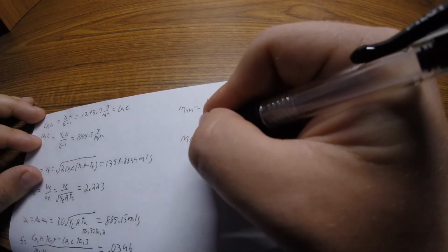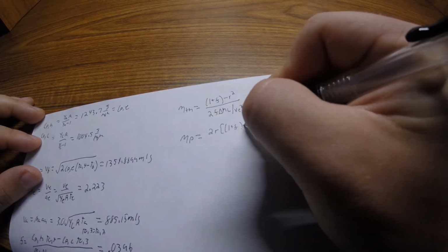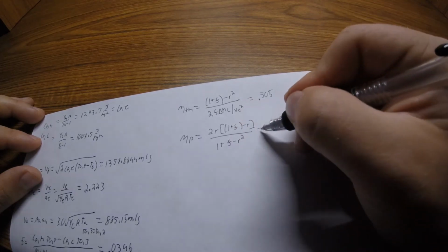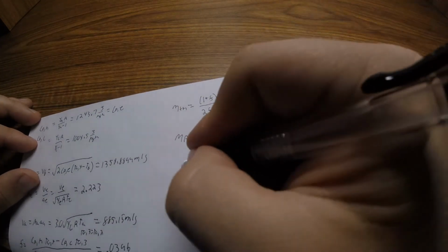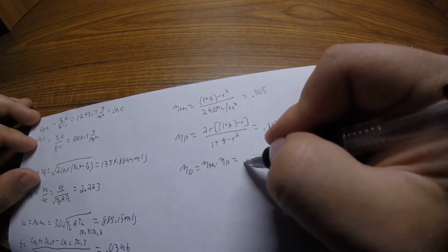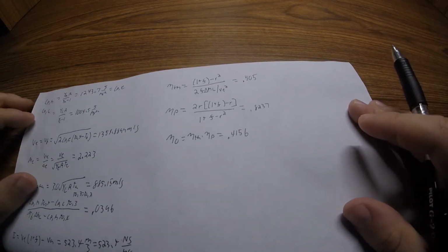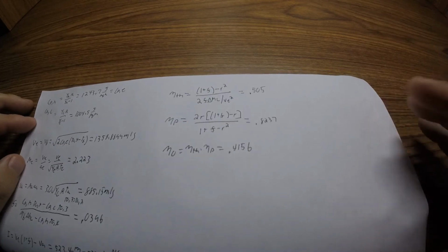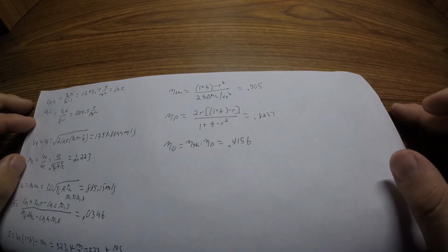And then our propulsive efficiency, with this equation, equals 0.8237. So these are very efficient. This will be a very efficient ramjet. That's our overall efficiency, thermal times propulsive, and that equals 0.4156. So pretty efficient for a ramjet. Ramjets are generally inefficient engines. They use a lot of fuel. They're not the most efficient, but they're really the only engines that can operate at huge speeds, very fast speeds. Okay, so I think that's about it.